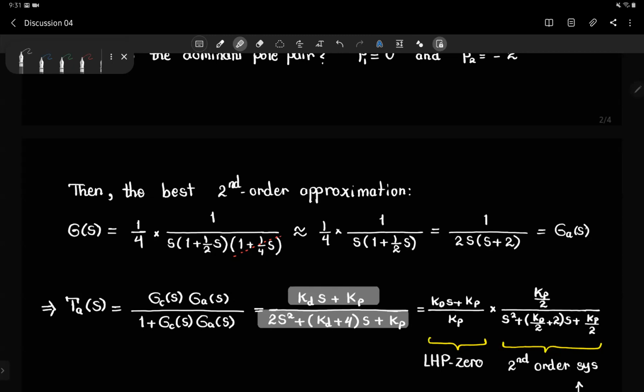If we do not take that into account, then if you pick Kp and Kd that satisfy the transient requirements for the second order system without the 0, when you look at the characteristic for the system with the zero, you will see that it will not be satisfied. However, we can deal with this because, as we said, we just want this zero to lie far enough in the left such that it does not affect the behavior of the system, right?